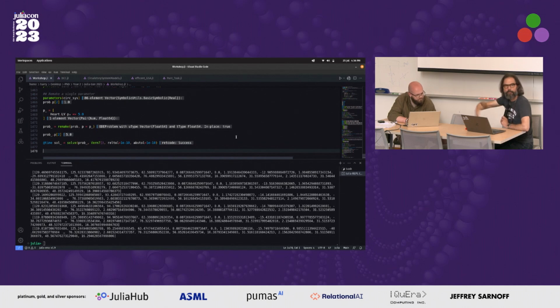Do whatever post-processing you need. If you want to integrate over pressure or want to optimize for pressure difference between two, or minimum over maximum pressure over time, you can do all of these operations in the loss function and then just return the loss or vector.